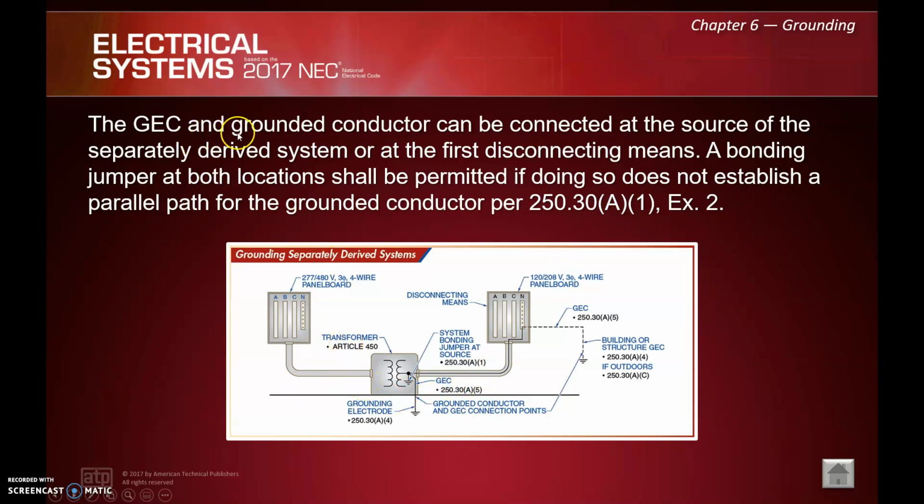So your grounding electrode conductor, again, think of your ground rod, your water pipe, can be connected, and yeah, sorry, the grounded conductor. So again, in most cases, that's your neutral. We have a GEC, we have a grounded conductor. What do we put between those two at our main panel? Most of us hopefully know at this point it is a main bonding jumper, right? We can bond at our first means of disconnect. You guys are used to hearing that terminology.